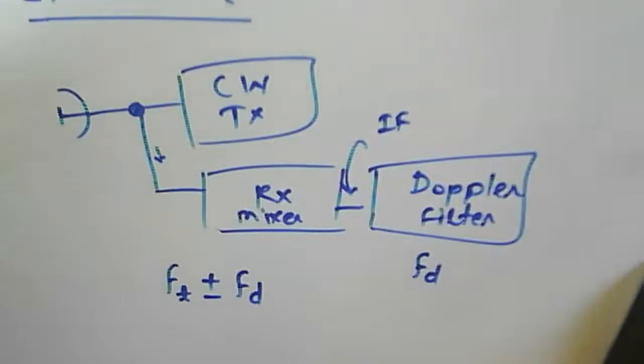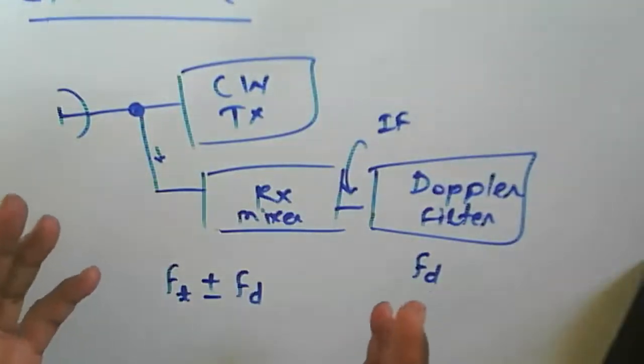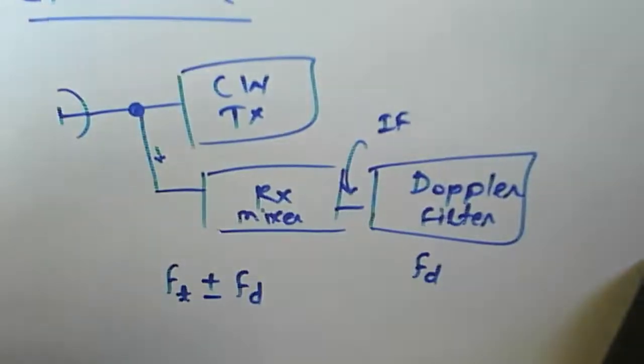Okay, so we need to talk about what will be the total bandwidth of this receiver, and what will be the receiver sensitivity. If we say that the band increases, if it works as a wide band one, then naturally it will decrease the receiver sensitivity.